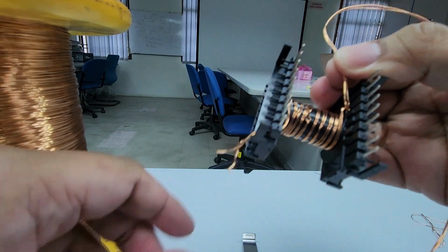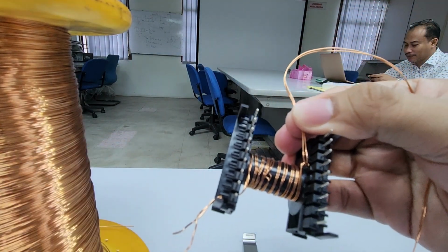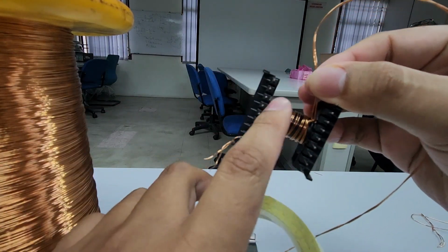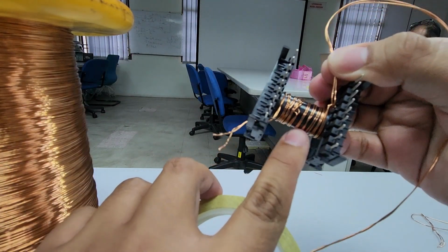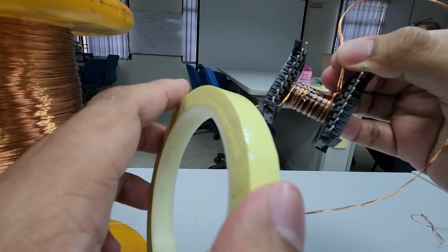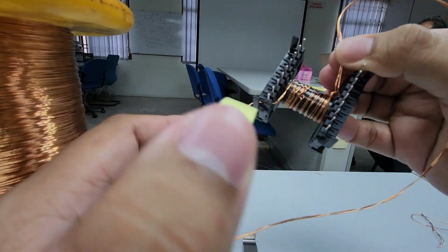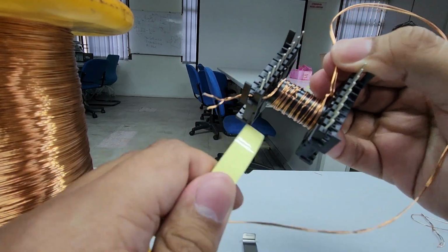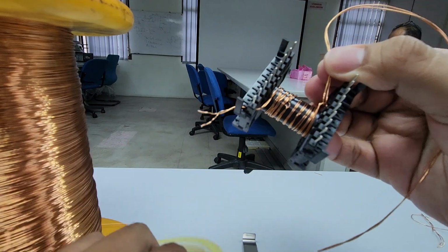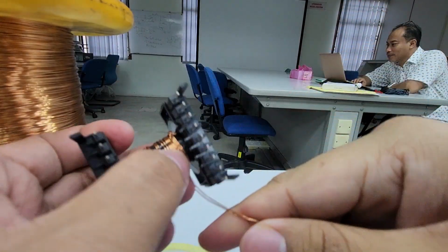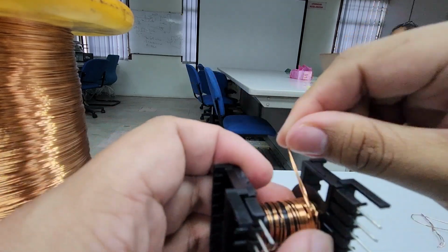And then if you have a lot of winding, you need a second layer. You have to put this tape, only one layer of tape. Do not make it very large, because you can lose a lot of things. A lot can be losses if you put this too much. Make sure you just insulate this and then do the second winding, and make sure the direction is the same. That one depends on the knot.